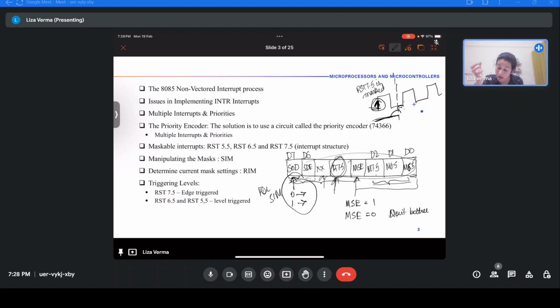If you're supposed to put something, 0 or 1, in SOD, and you're not interested in sending serial data and are only interested in masking the interrupts, what will you do to prevent sending that serial data? We'll write 0 to SDE.